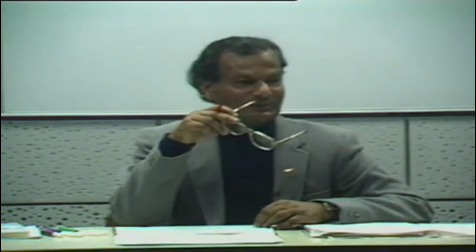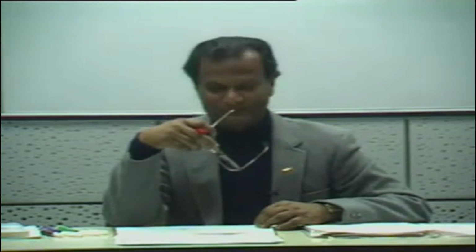Alright. Usually in measuring instruments, which can usually be modeled as a second order system, what do you think we should have as far as damping is concerned? Critically damped. Well, why not under damped? Let's understand. If we have an under damped system, then it keeps oscillating about the actual position, and we don't get the exact value in a small time.